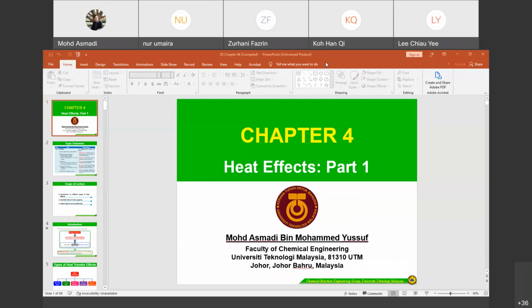So it depends on what equation you can use, whether ideal gas or virial equations. Virial is applicable for low to moderate pressure if it is truncated at two terms, right? And for three terms truncated, it is applicable for high temperatures, even for high temperature up to 50 bar. And for the moderate it is around 1 to 15 bar or 20 bar. 10 bar is also considered a moderate pressure.